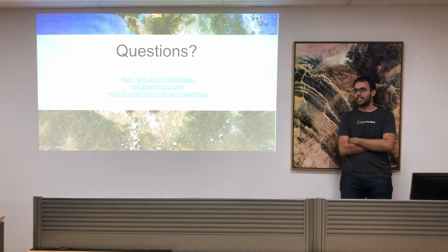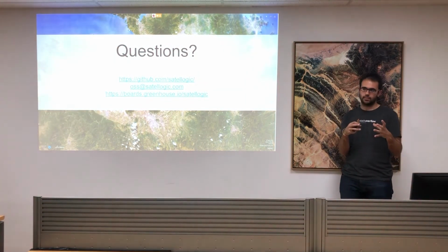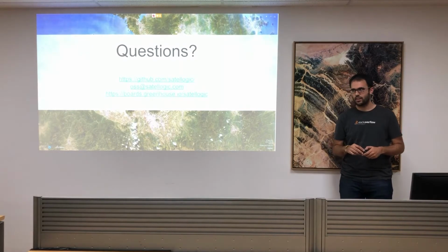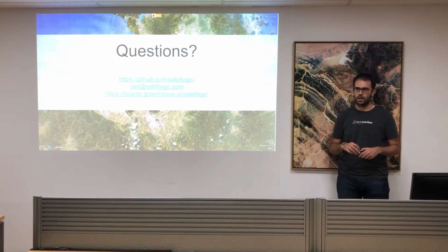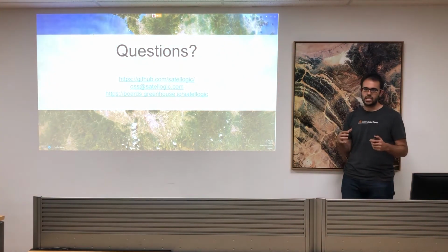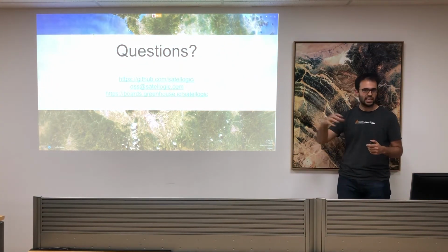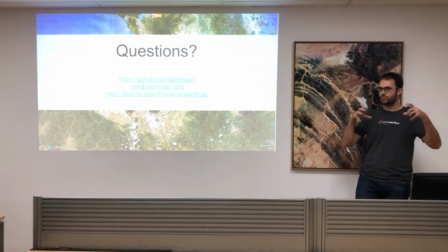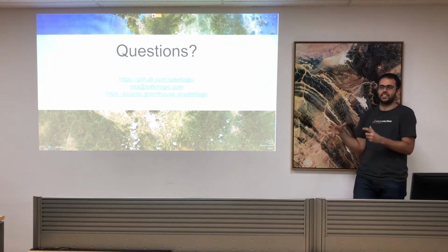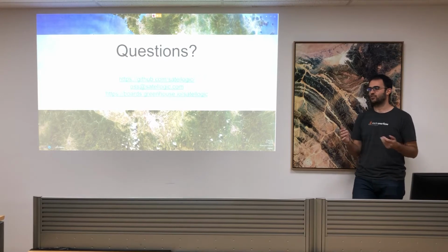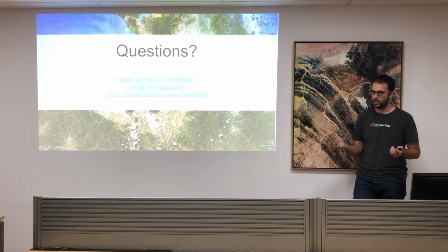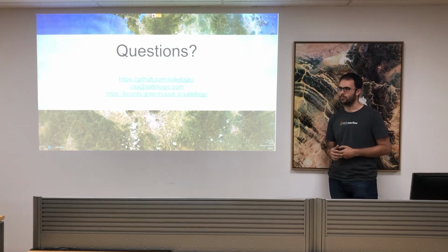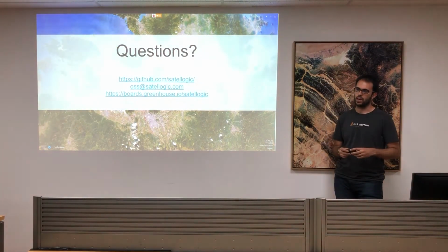We have an engineering model in the factory in Uruguay that is a satellite very much like the others, but it's standing on the ground. And we can test lots of stuff there, but there's one specific thing we cannot test, which is the maneuvering stuff, because the satellite needs the GPS data and the magnetic field of the Earth and then information from the sun sensor and from the star trackers. So there's a bunch of information that the satellite is using to know where it is and where it is pointing to. And basically we have to fake all of it in some very nasty way. So it kind of works, but it's not foolproof. We're trying to work on better ways of doing it, but it's something that we are currently struggling with.